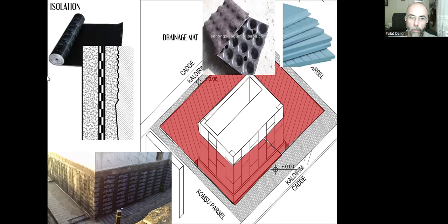So instead of the plaster here on the surface, we can have our XPS boards that will protect the membranes, and they will provide heat insulation as well.